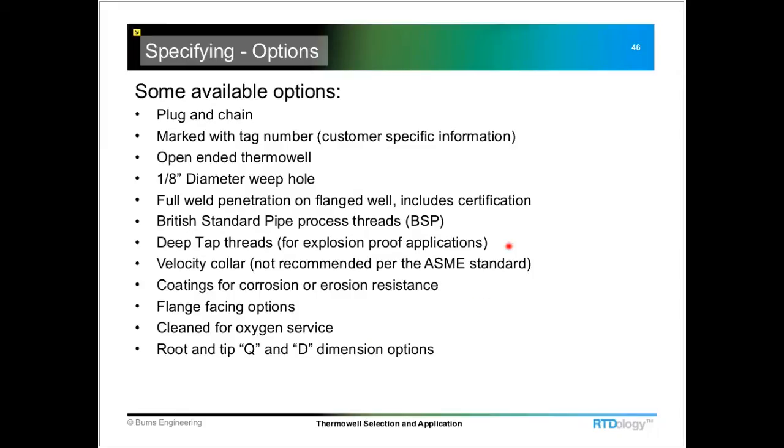One of the ones that is common for flange Thermowells would be a full weld penetration where the flange is welded to the stem of the Thermowell. And that can be certified, and also usually when that is specified, I see customers requesting either an X-ray inspection or even a dye penetrant style testing, just to make sure that it's not cracked and that it's got a full penetration weld.